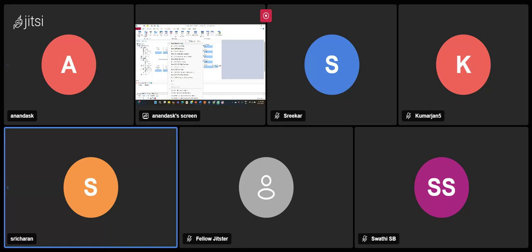We can create that network node manually, or through the CANoe configuration: in simulation we have a model wizard, and when we insert the network database, all the nodes will be created automatically.